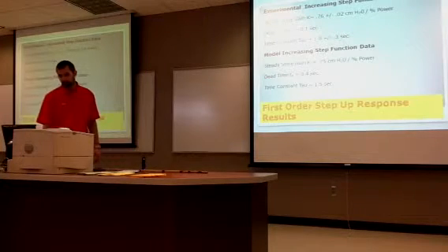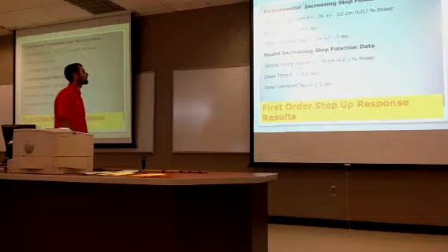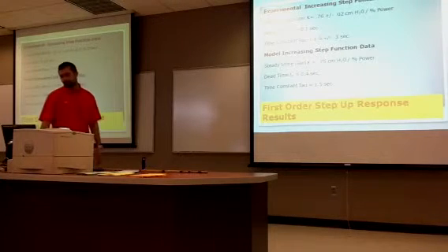On the step up, we ended up with 0.75 centimeters of H2O per percent power, a dead time of 0.4 seconds, and a tau of 1.5.